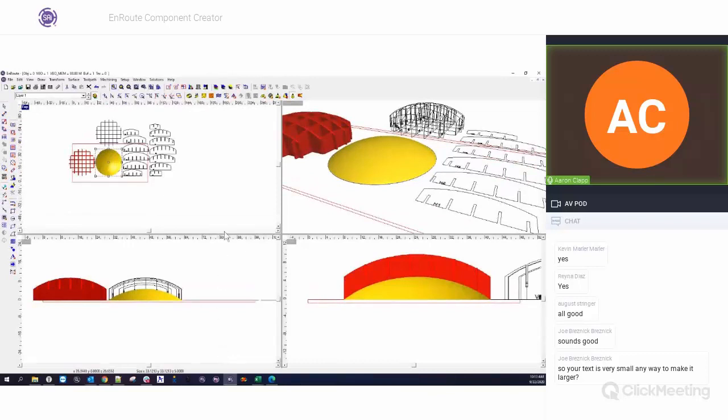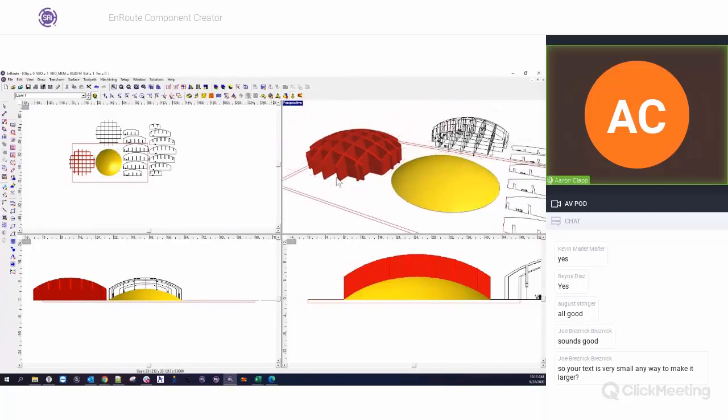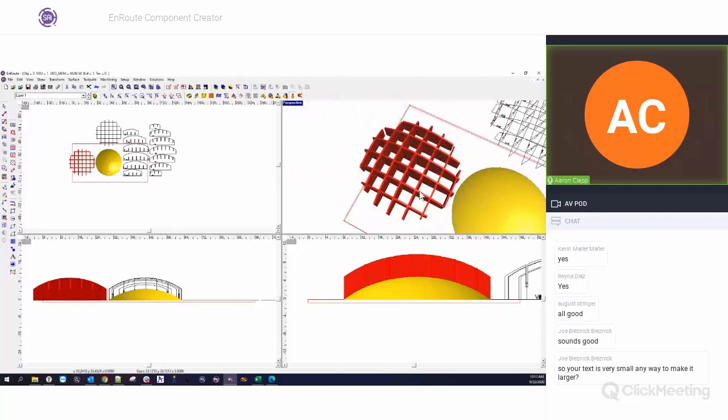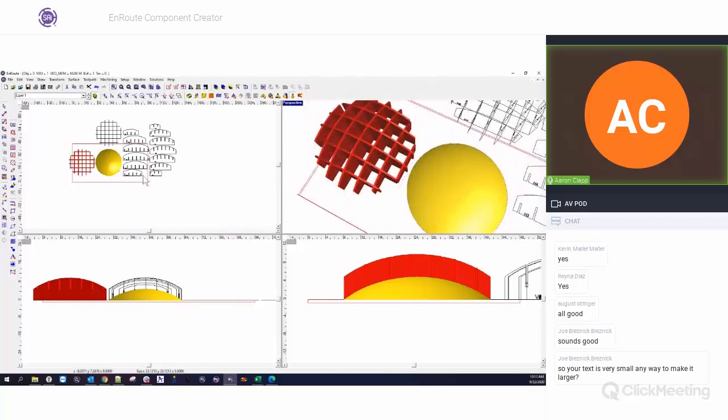So what this has done is it has taken this conical shape, and since I told it to go 5 inches tall, it's going to add a 5-inch return on the height of this. If I put it at 0, it would have exactly followed the shape here, but I added 5 inches. So now we've got a nice rounded pattern here, and then I've got all my parts